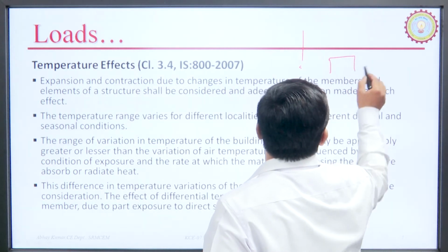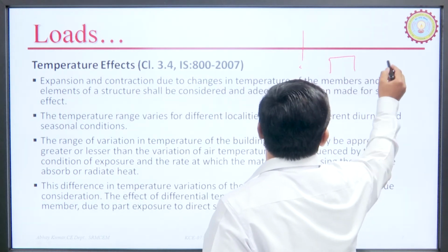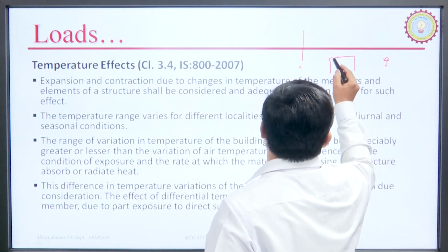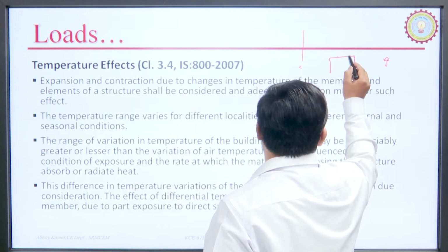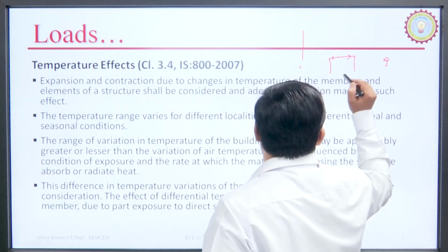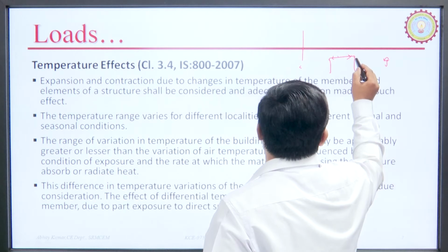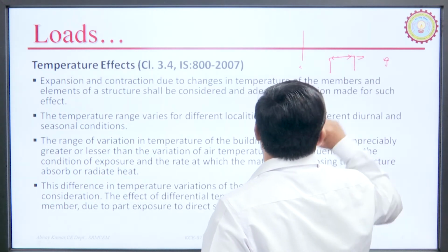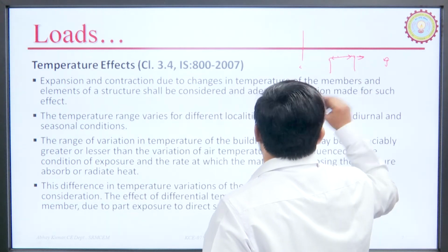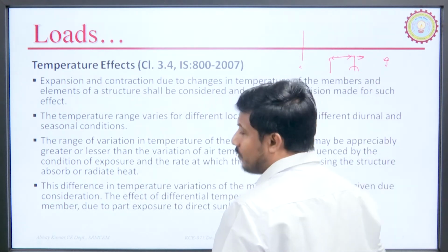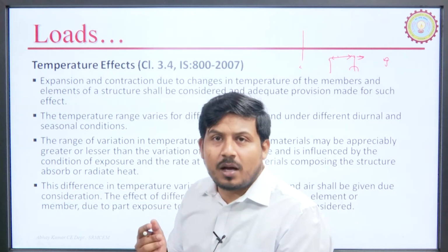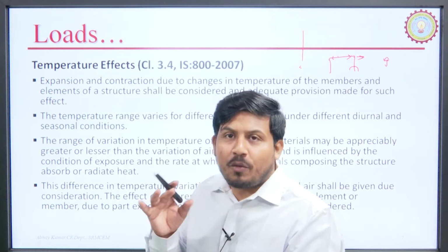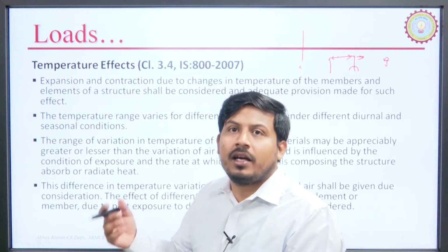Okay. There is a beam and there is a column, these all are made of steel. If we increase the temperature of this system, or increase the temperature of this beam only, then this beam will try to expand, and while expanding, this beam will produce some force on this very column in that direction, and because of this excess force, okay, there will be a moment on this column. So, through this example we can see how this increase in temperature is incorporating some forces in our structure.